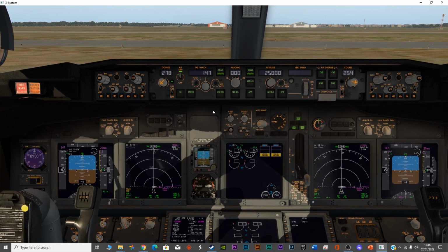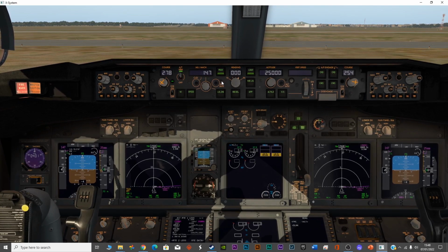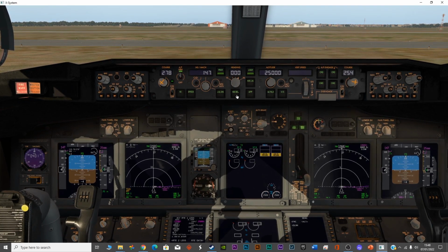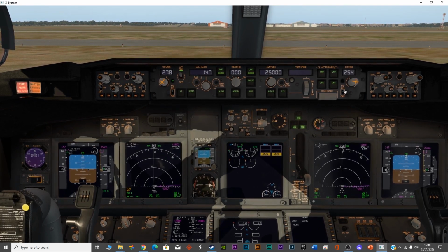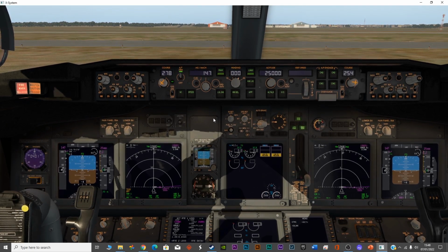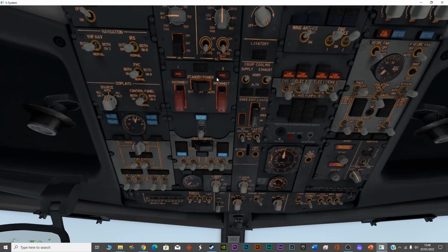So that's it. But after turning on the autopilot, the plane will automatically follow the flight path and all the speed profiles and the descent and the climb profile. So I will not be using the heading and the speed options, but if you want, you can use this. Flight directors on, auto throttle armed. Very good. Anything else? Now, some last checkups.